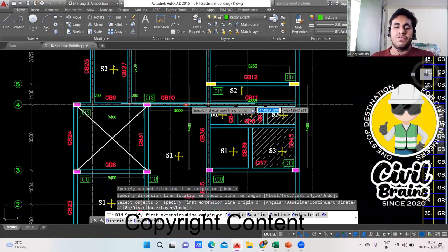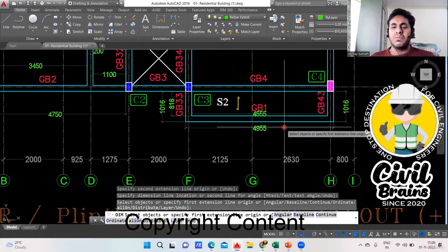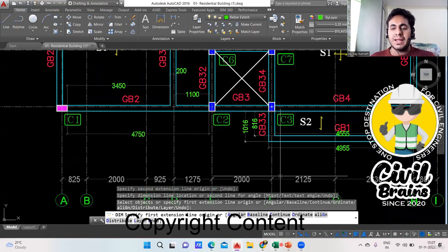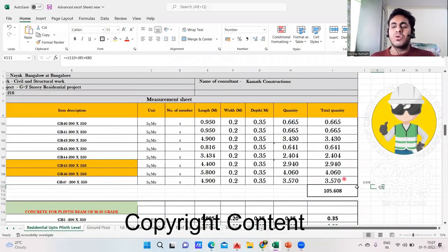Nowhere will you have any confusion. You always go with one by one beam. First you take GB1, you go with GB2, you go with GB3. Even though it's time consuming, it's okay. You'll never go wrong anywhere. Okay, that's it. So I hope you have enjoyed my lecture up to here. You got a complete idea how the shuttering quantity has to be found out, and try to apply those things.